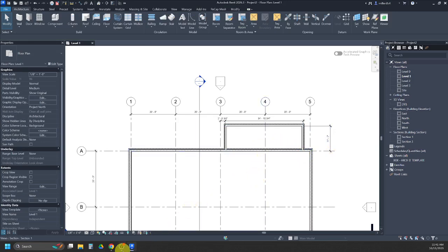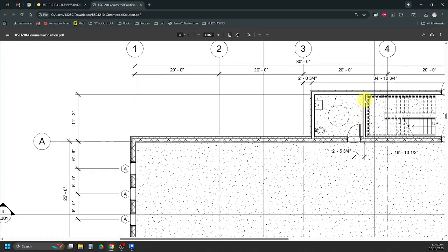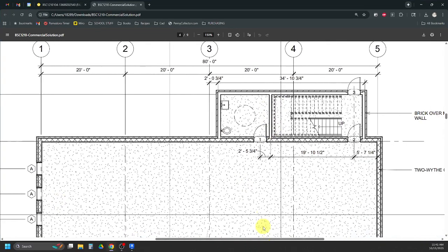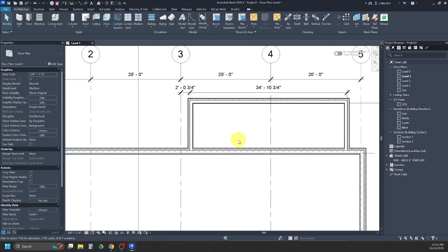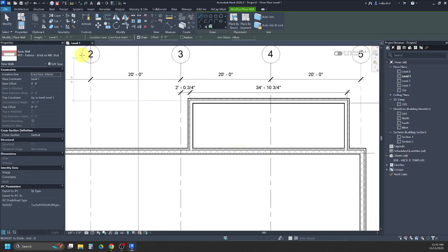We'll also, while we're here, I'll place this interior partition wall. For the time being, it sits somewhere a little bit skewed to the left of grid line 4. So back in Revit, I'm going to start the wall tool, which is keyword shortcut WA.